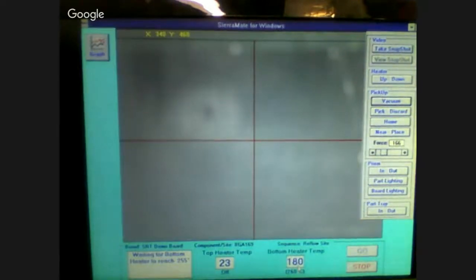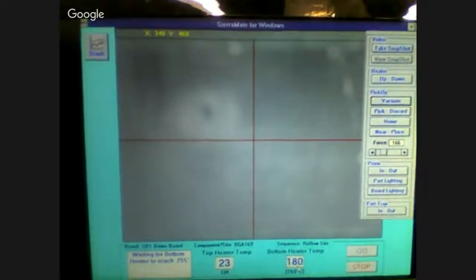Again, our bottom heater is wrapping up here. These bottom heaters are pretty massive. There's a lot of metal to them, so it takes a few minutes for them to heat up and come to temperature. And I like to get my bottom heater pretty close to temperature, which I said we're doing 260, then we'll ramp up 30 more C to 290.